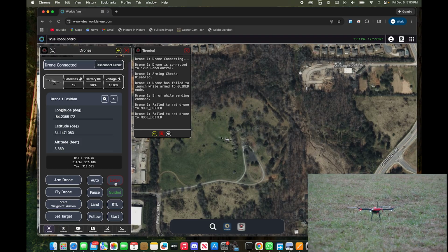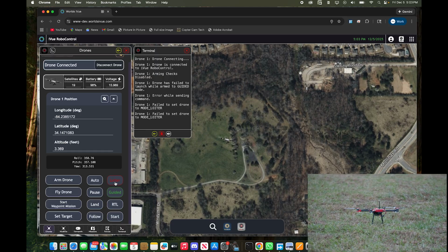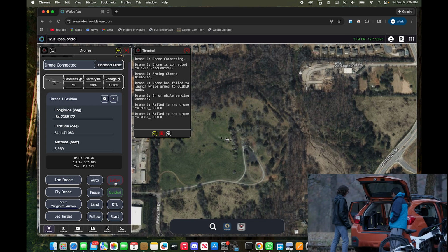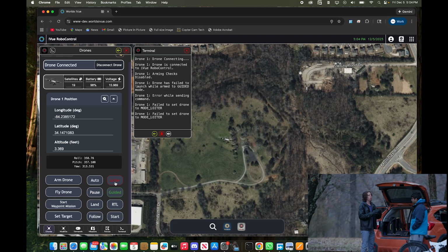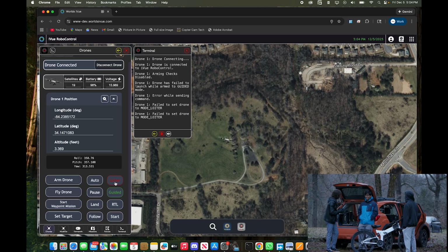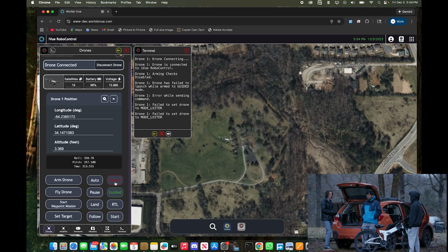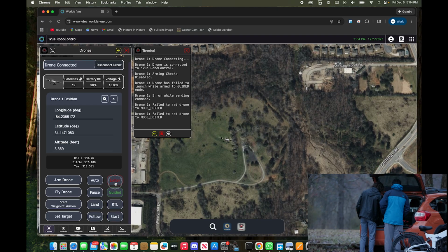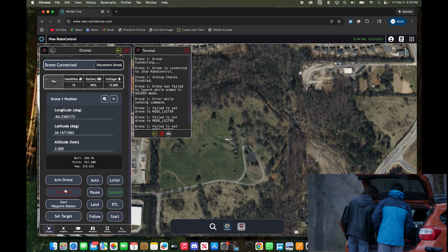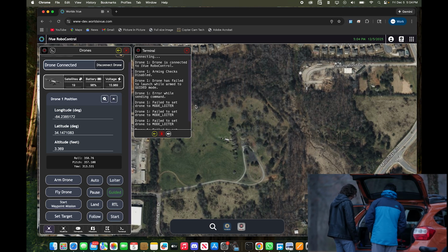All right. I believe the issue might be, yes, the same arming problem we had from last time. You can see we make great drones, but drone control software, on the other hand. I'm one person. What am I expected to do? Okay, so it seems like there's a problem with it arming. There might be a chance that it's timing out. Maybe, I'm not sure. I did change the timeout from 2 seconds to 5 seconds. But, I mean, we're able to arm in QGroundControl just fine.